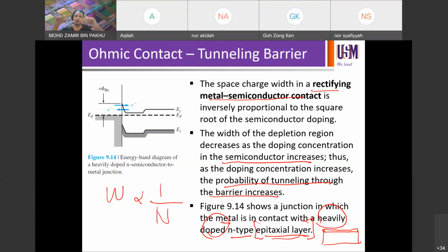You will learn this a lot more when we learn about 487 later on, for applied. When you learn about film deposition techniques, how do you do deposition? By sputtering, by evaporation, thermal evaporation, electron beam, MBE, spin coating, all those. Different deposition methods have different natures. Certain methods deposit many molecules together at the same time.